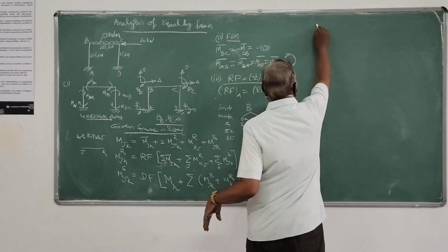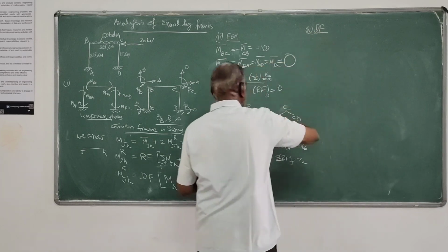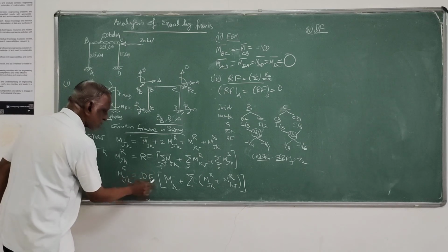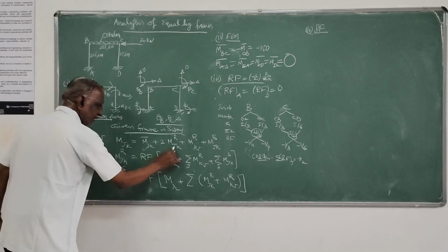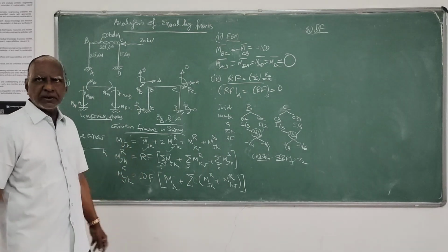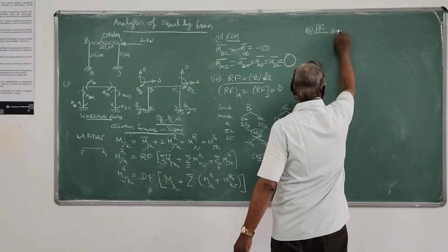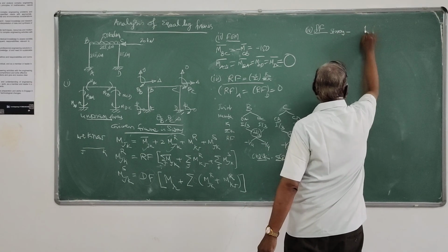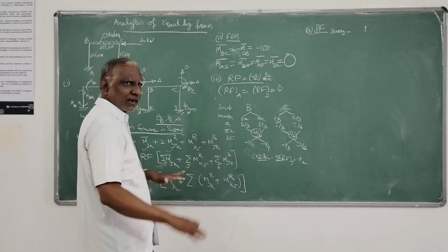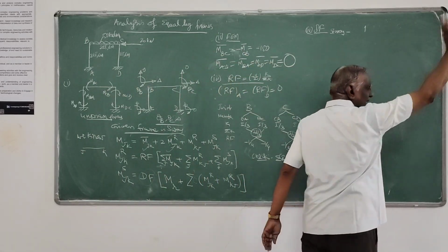Next you have to find the displacement factor, that is the fourth step, which is extra from the previous example. This is done, these fixed end moments, they are all known. Here the displacement factor has to be determined. I have already told how to find it out. You prepare a table, write the story number. So here it is only one story frame. Earlier we had 2 stories. You can take that number of stories, 1, 2, 3 like that.